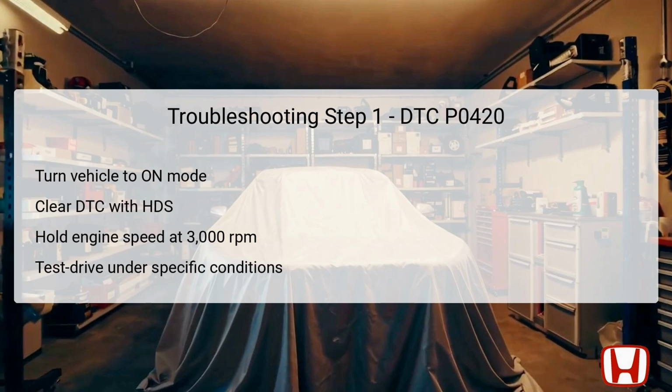This step is crucial as it helps the PCM gather necessary information regarding the exhaust system's performance. After holding the speed until the radiator fan activates, allow the engine to idle. Following this, execute a test drive under specific conditions, including ensuring the engine coolant reaches over 158 degrees Fahrenheit.